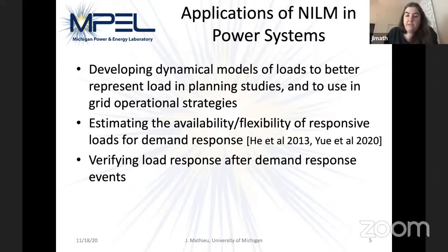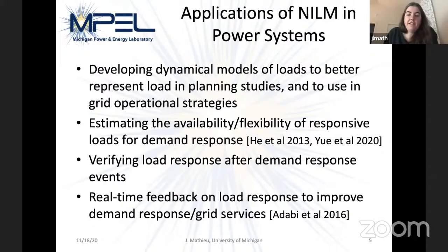You can also use non-intrusive load monitoring for verifying the load response. So after there's an event, when you ask a load like an air conditioner to shut off, you can look at the smart meter data, for instance, to see if it actually responded the way you expected it to. And lastly, I think the one that's the most exciting is to get real-time feedback of the load response from the smart meter data or the existing meter data, so that you can understand if the load's responding the way you're trying to actuate it to respond. So that if it's not responding, you can change how you're sending that control signal out to get it to change its behavior and hopefully respond more in line with what you were hoping.